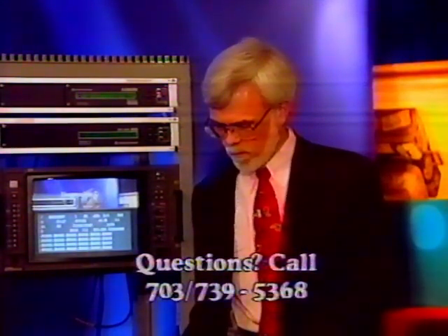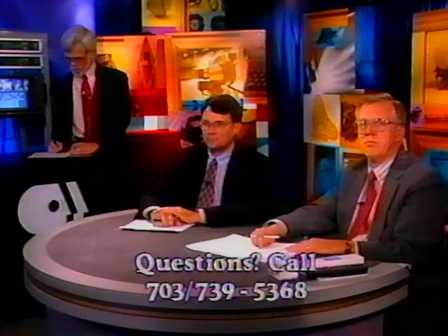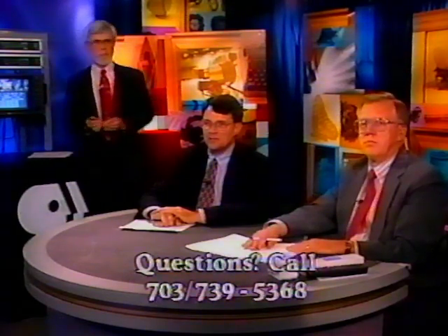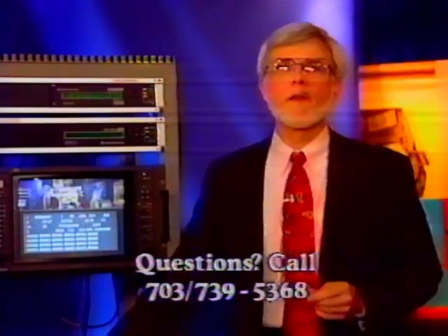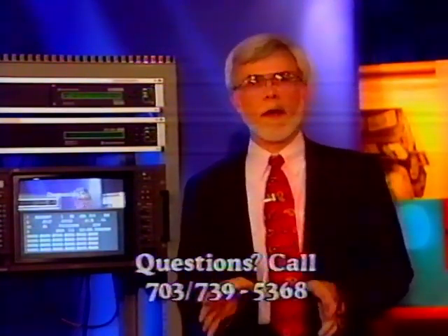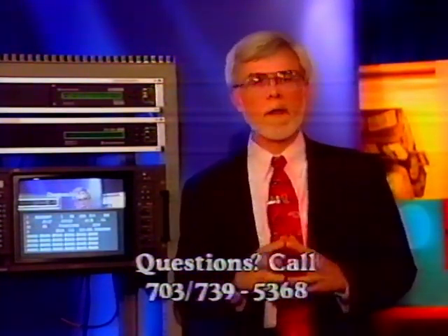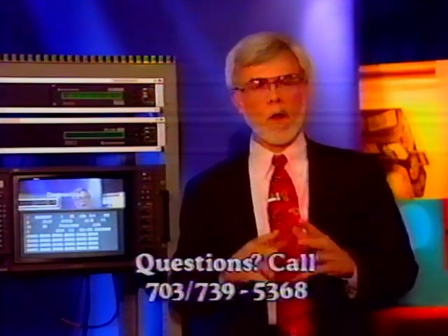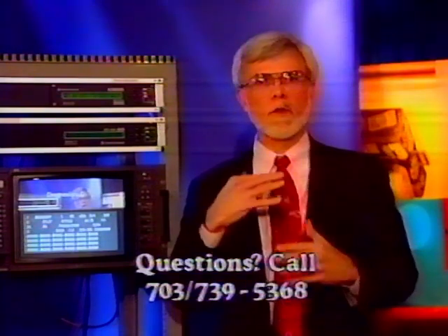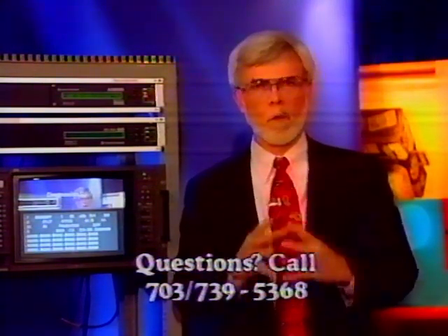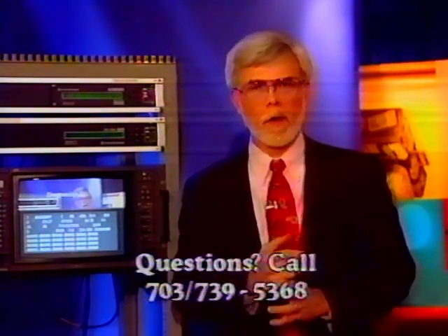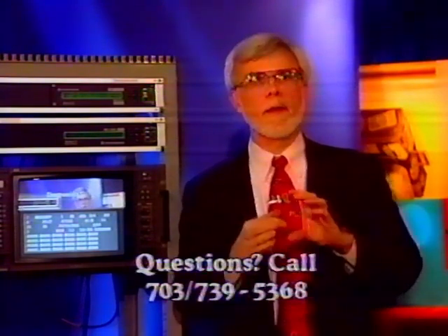We did have to manually tune all our IRDs ahead of time, and then when it found this mapping, it worked fine. We did leave it overnight, and it did not lock in. Yeah, that's something you do need to be very careful about. The IRD, the 4000, is going through and checking all sorts of different combinations, looking for the right combination of forward error correction rate and symbol rate and frequency.